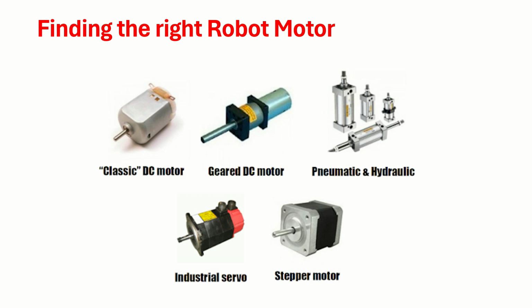And also I was telling about the displacement part. How accurately I can make a displacement, by how many degrees angular displacement I can make. So again, that also depends. So feedback, displacement, in short accuracy, and the amount of load, that's the torque. These are all parameters you have to consider while choosing the right robotic motor.